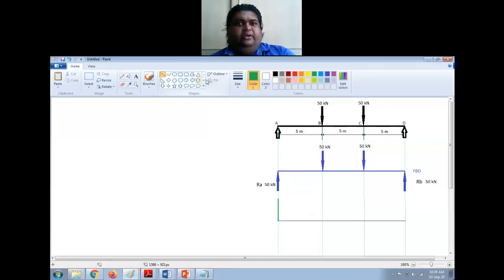That's all. Okay. Now, between A and B, there are no loads. There is no load between A and B. So I will draw a horizontal line from A till B. Now at B, I have a 50 kilonewton load which is acting in the downward direction. So at B, I will draw another line of 50 kilonewton down. So 50 kilonewton, it came down.